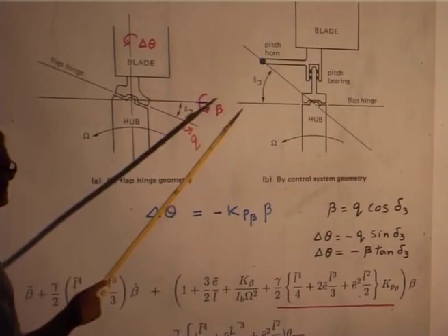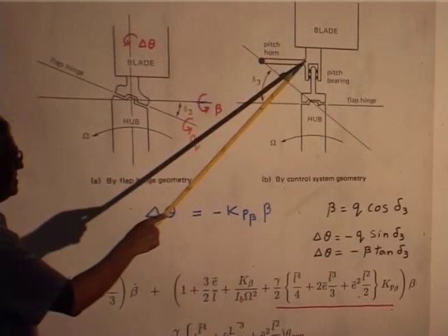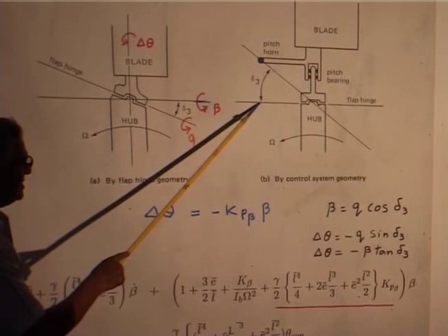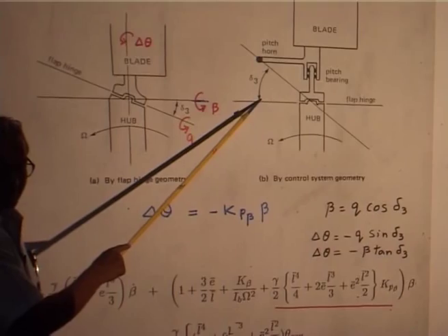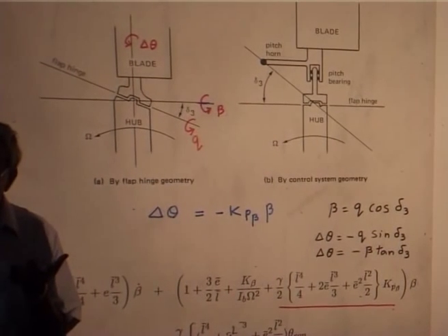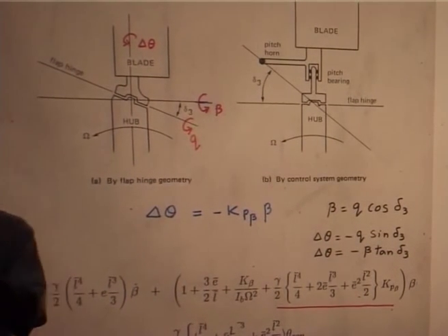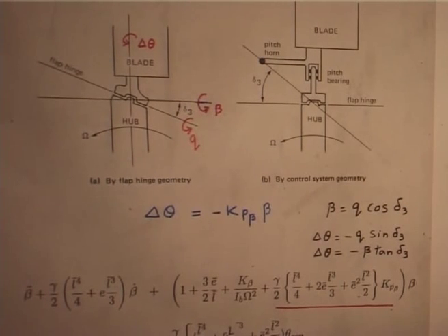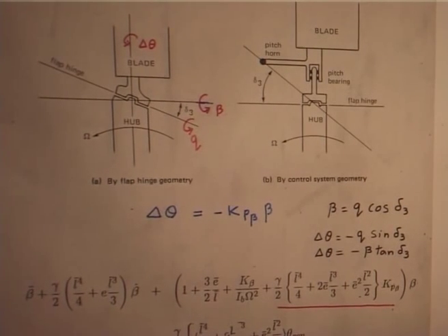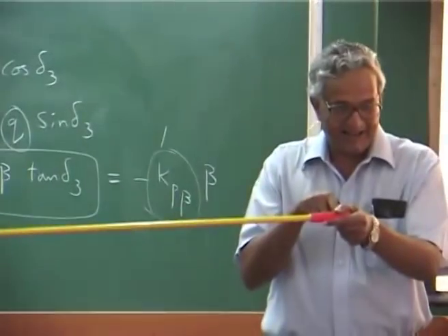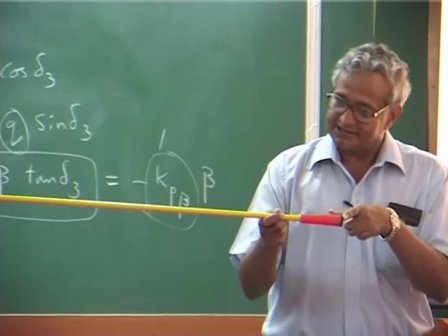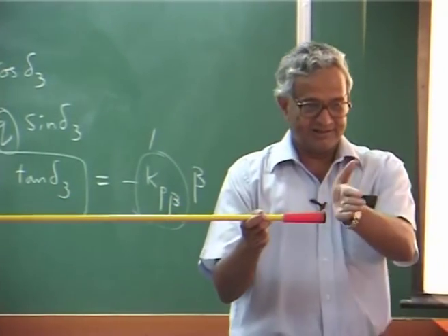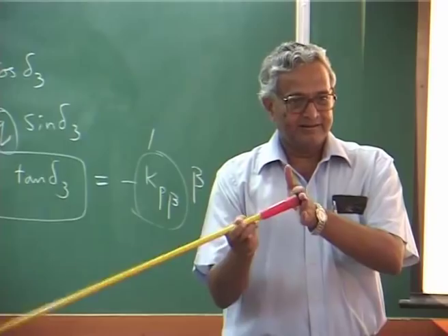Suppose if you take this horn, instead of putting it here, you bring it up to this point and then connect it here like a 90 degree, then it flaps, no problem. That is why in most of the designs, the pitch link, they will take it like this, bring it back to the axis, and from there the linkage will go. Then these 2 points are in the same axis, in the sense one horizontal, so it will do.